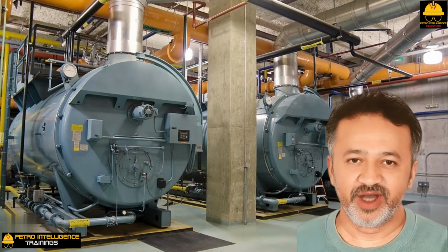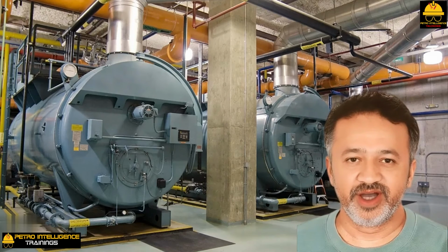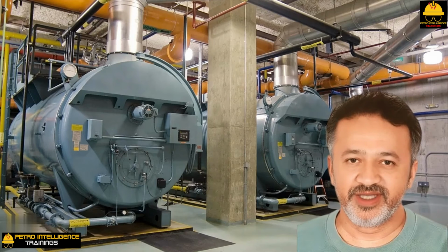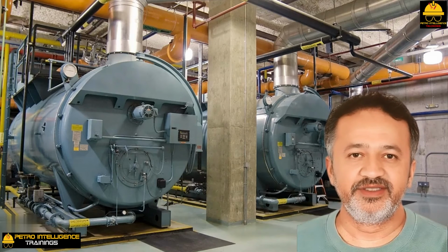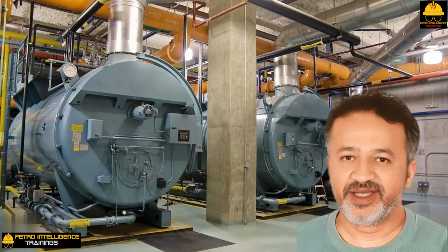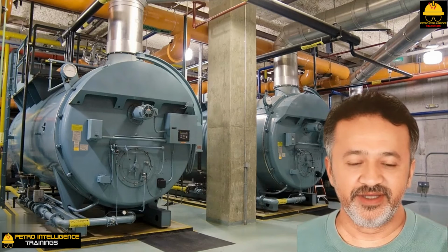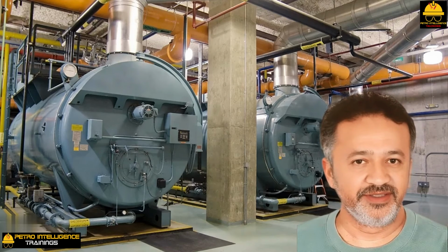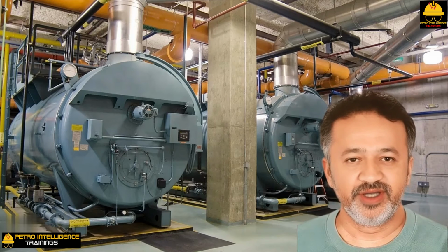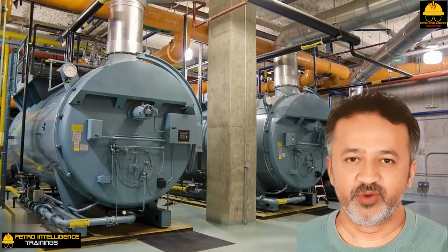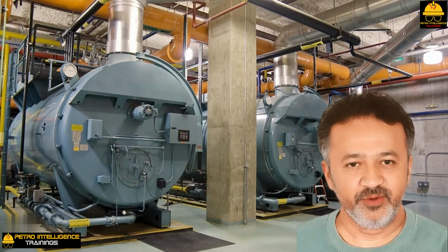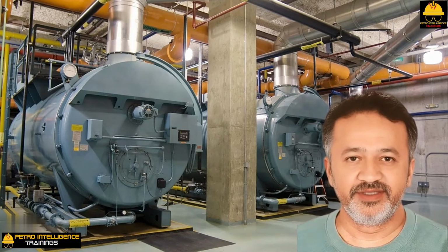The answer is that air preheat requires less fuel gas firing, and thus less flue gas and hence less heat pickup in the convective section. While the radiant section heat transfer rate will remain constant, the heat transfer rate in the convective section will drop in proportion to the reduced fuel gas fired. A 200 degrees Celsius air preheat, from 20 to 220 degrees Celsius, will save 10% of the fuel and thus reduce the flue gas flow by the same 10%.